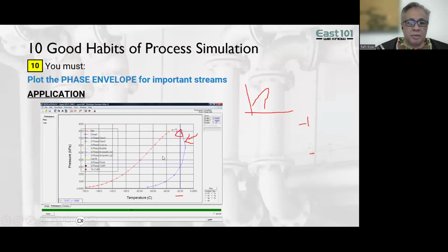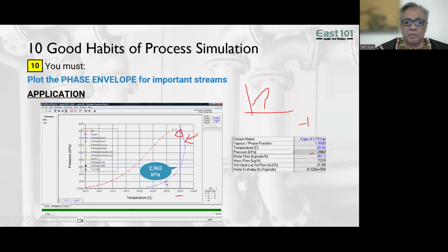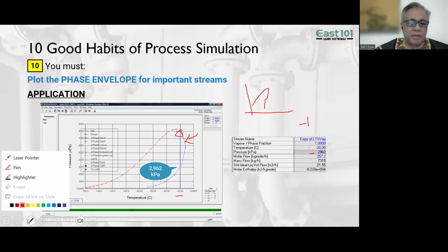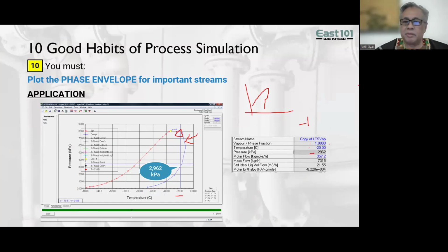Okay. So if you take a look at this case over here, I actually have two dew points. One over here, this is called my dew point. I'll use the term dew point to describe this. And this dew point here occurs because of the retrograde region, because you have this bulge. Normally, if you draw your phase envelope, you might expect something like this. I'm drawing this with a mouse, so it's not really that specific.